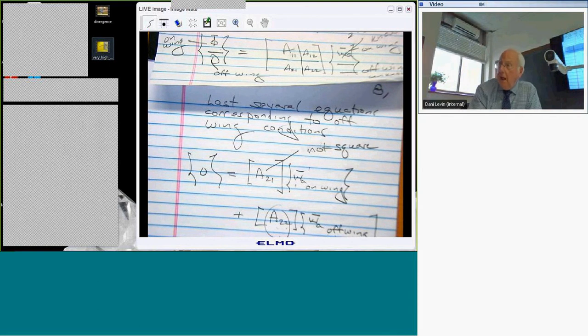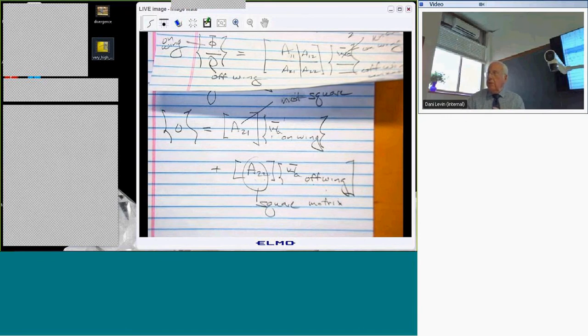Okay. You'll be pleased to know that there are companies that make a very good living providing you with software that does all that. And this is a little tricky because the Mach lines, if you look very close, these A functions are singular along the Mach lines, but they're weakly singular. That is, they go to infinity like 1 over the square root of the thing that's going to 0. So you have to be careful about how you construct the boxes and how you evaluate the coefficients in the A matrix. And that required someone doing a fair amount of hard work to figure that out.